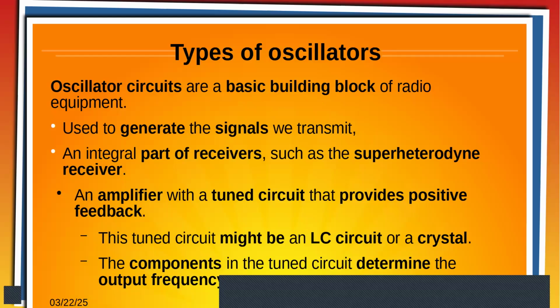In order to provide long-term oscillation, it has to have a feedback gain slightly higher than 1. If it has too much gain, it won't continue to oscillate. If it doesn't have enough, it won't oscillate. And you have to have higher gain to get it started. They're finicky little things.